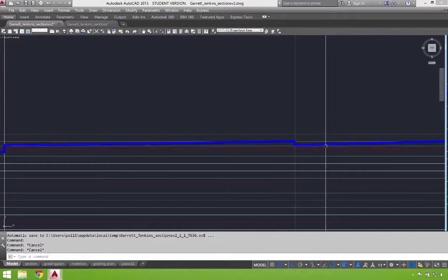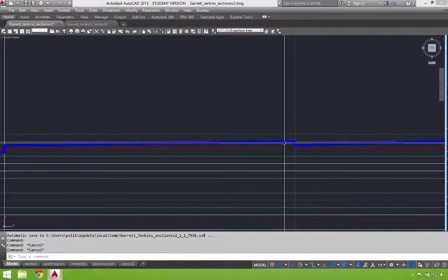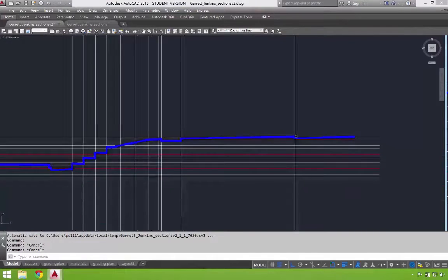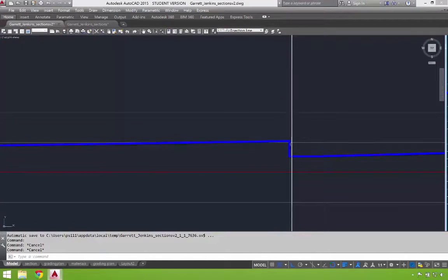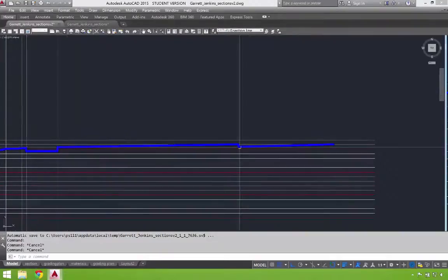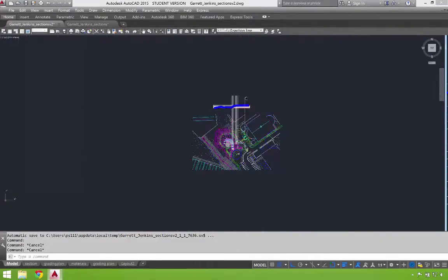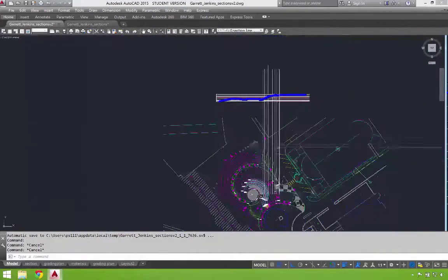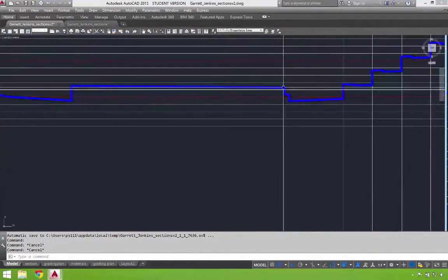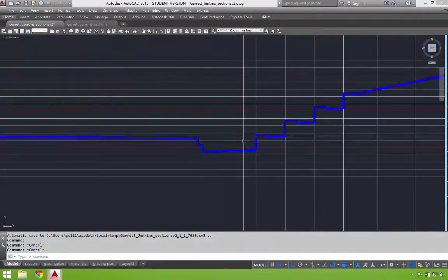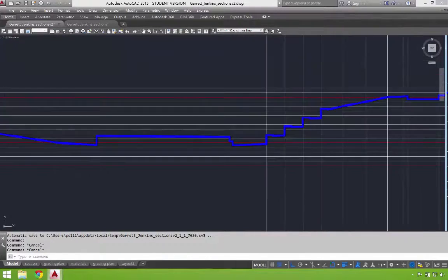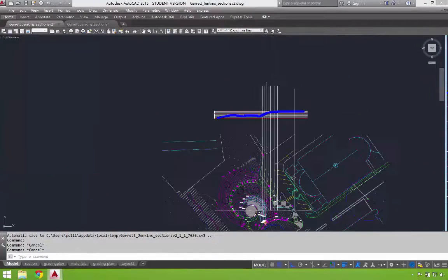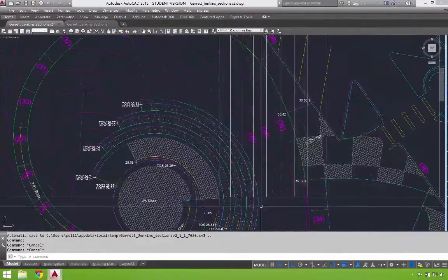really give character to the section line that you're actually creating here. And it's things like a 6-inch curb, right? So we've offset this down 6 inches or half a foot to show the back of curb that happens in this area. So there's a lot of little things that you want to make sure to pick up on, whether it's steps or walls, even subtle slopes that are actually going to reinforce the intricacies of the design that you're proposing.